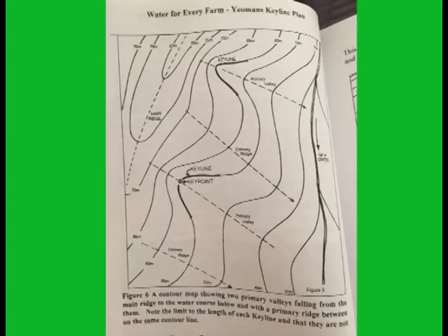So this would be according to Keyline plan. You go in the valleys, parallel down, reference on the ridge, parallel up. How do you deal with secondary valleys? Never talks about it. Never talks about how to deal with secondary valleys. Well, let's make it spread from there to there. This is done according to the book. Is this different than the one I showed you earlier? Yeah, it is, isn't it? First of all, the whole system is designed around a thing that's not really a key point. But the water still migrates towards the ridge.